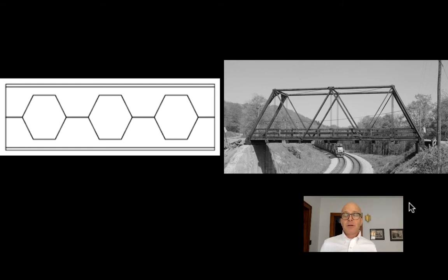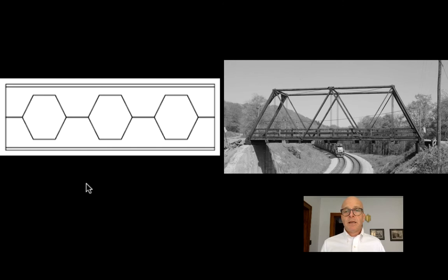Now, the other thing we can do is that we can manufacture beams out of very, very small flanges and very, very lightweight webs. And there's not much difference in terms of the mechanics of the beam between a castellated beam and a vector active structure like a truss. In this case, you can see that in the castellated beam, we have a compression flange at the top, and in a truss, we have a compression chord.